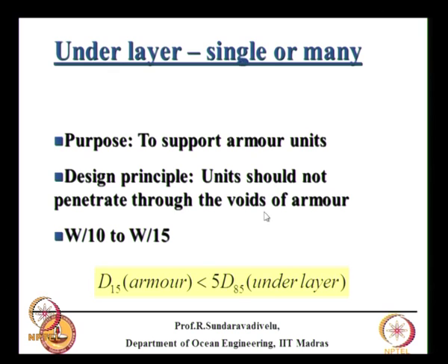That is the purpose of armour, this underlayers. The design principle is the unit should not penetrate through the voids of armour. Suppose there is a void in the armour, this should not penetrate through that. That means the weight distribution. See, when you do the breakwater construction there are 2 issues involved: one is transportation of the rock materials from the quarry, another is placement.